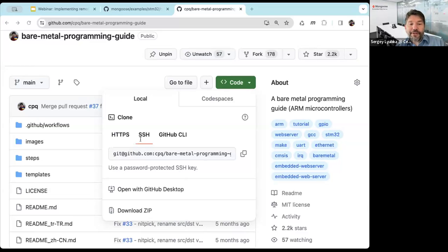You see, this function starts from the address 80022C, right? So why this address? How do we know that this is the address? Because the linker script tells us so. If we look at the linker script, we see that the flash starts from address 8 and then 6 zeros, right? So that means all functions like main and other functions will be at that memory region. So I guess this is clear to you.